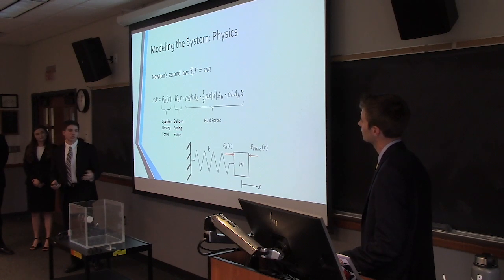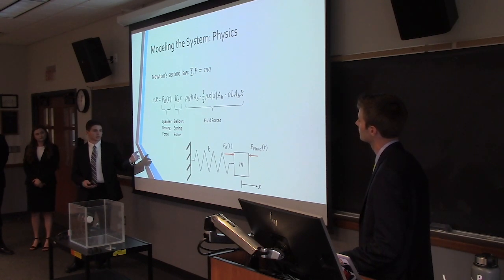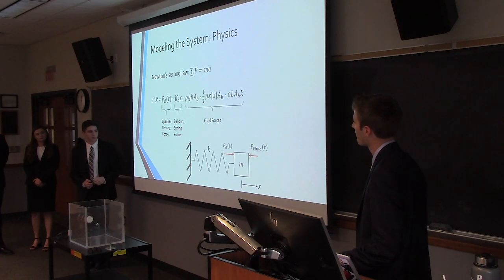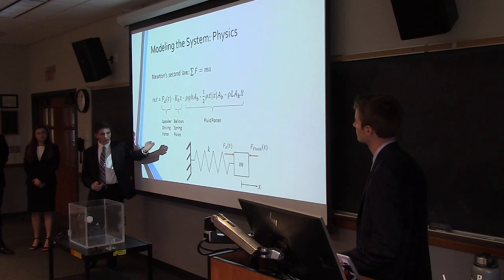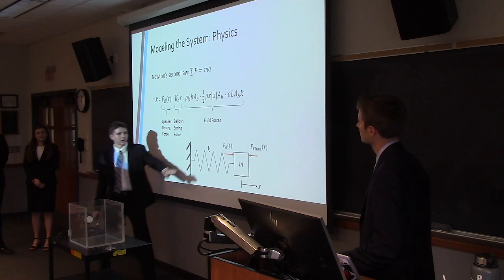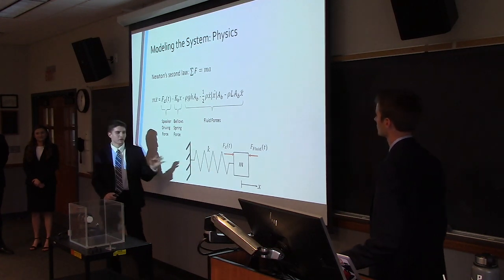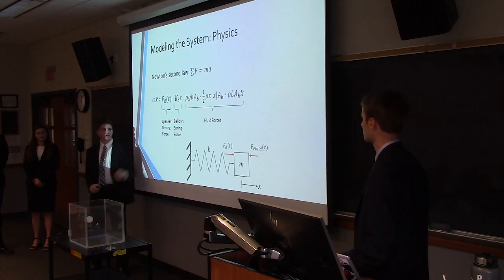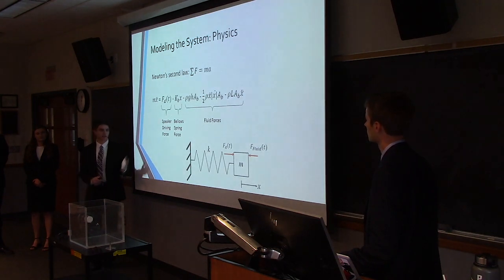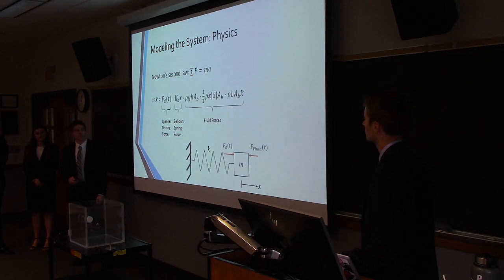In modeling this system, you can think of it as a simple mass spring oscillator, as shown by this diagram. So you have the driving force from the speaker here as a function of time moving the mass. There's the fluid forces as a function of time opposing that, as well as the spring forces opposing that.